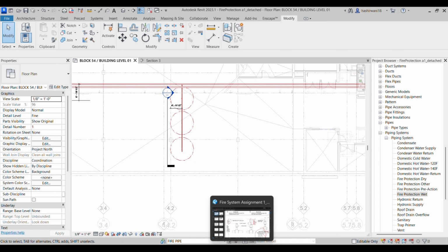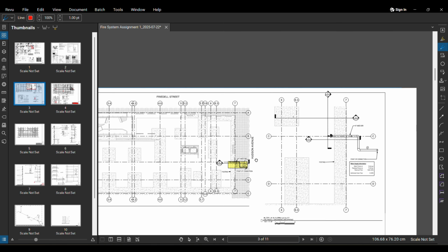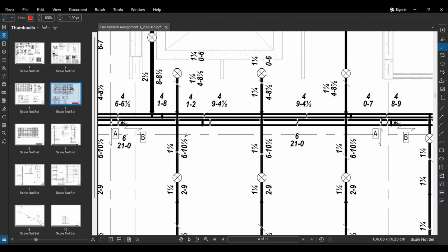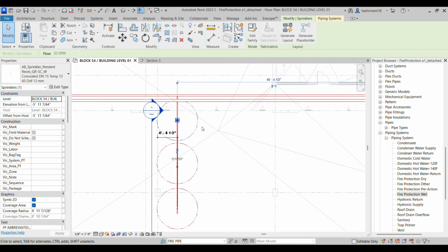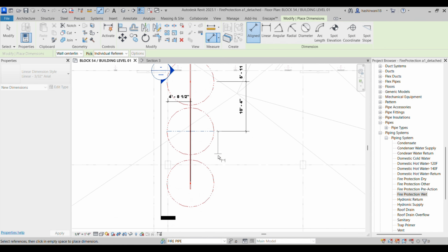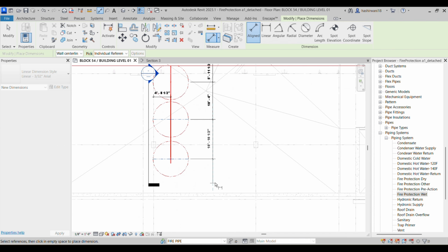Now one thing that we need to make sure is the spacing. I go here, and now let me place it according to these spacings here. We have 6 feet 10.5 inches. I'll select this pendant, and I'll just give dimensions first from the center line, and then this, and then center line to this, and then center line to this, and then control Z it here to here.